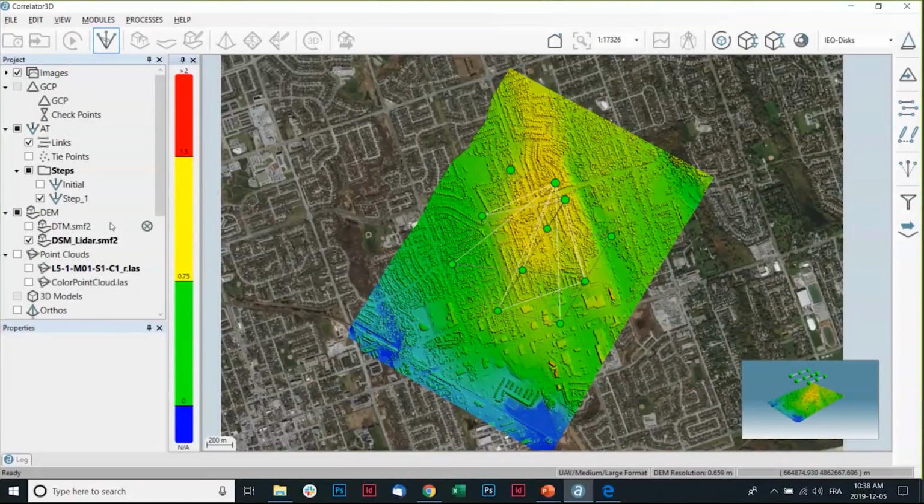If you're not familiar with the difference between the true ortho and the classic ortho, the main difference is that if you're doing an ortho on your surface model, all the leaning effect of the elements on your imagery will be rectified. So the buildings, the cars, and everything that's over the terrain will be rectified, so every pixel is seen in an orthogonal perspective.